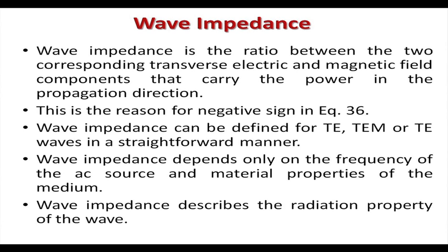What does it say physically, what is wave impedance? You see, for plane waves, the wave impedance is always 377 ohm. Now, what is the physical meaning of wave impedance? It says that when a wave is propagating, what is the relative strength of electric field and magnetic field. And we say that if wave impedance is higher than 377 ohm, then it is a high impedance electric field. High impedance electric field means electric field is much stronger than magnetic field. So, for a high impedance field, if I want to measure, then generally we use an E field probe.